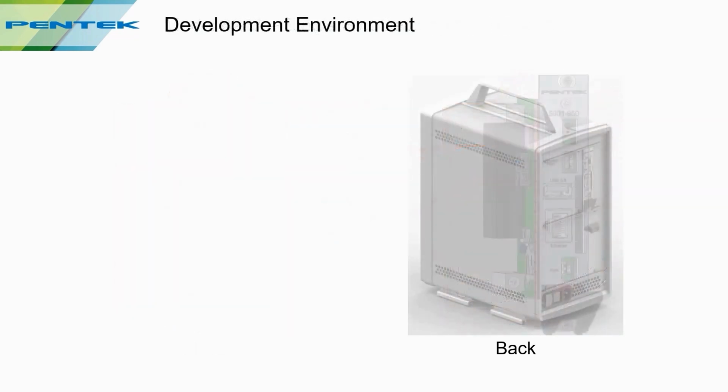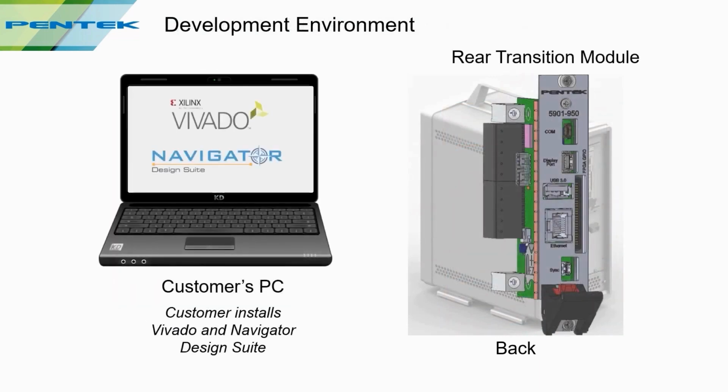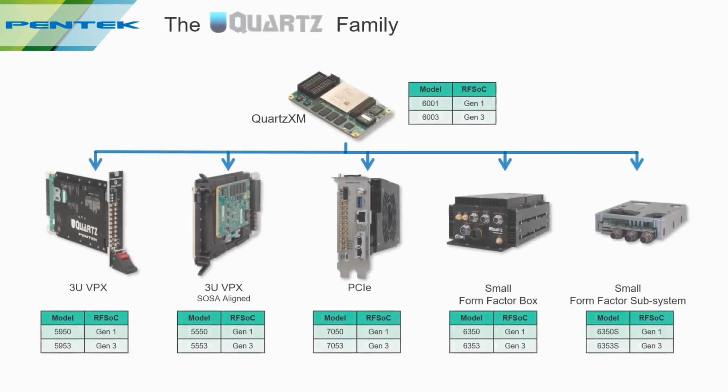And what the environment looks like is a PC with Xilinx's Vivado tools installed, the Navigator Design Suite from Pentek, which is the host application development package. It's a BSP for the board, as well as the FPGA IP libraries. There are multiple interfaces that can be used between the development PC and the RFSoC board, but the simplest is Ethernet. When the RFSoC board powers up, it boots Linux, and you have access to the board's resources through a terminal session.